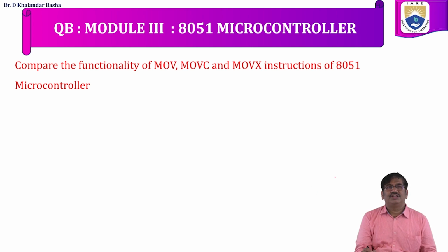The next question is compare the functionality of MOV, MOVC and MOVX instructions of 8051 microcontroller. So all three belong to the data transfer instructions only. If you have a MOV instruction, the data we are going to be transferred within the 8051, either it may be a register to accumulator or B register or any memory location.